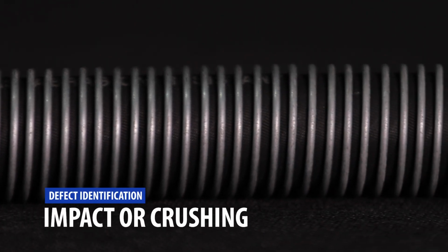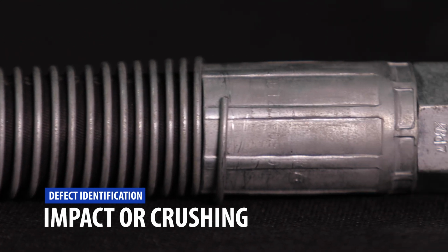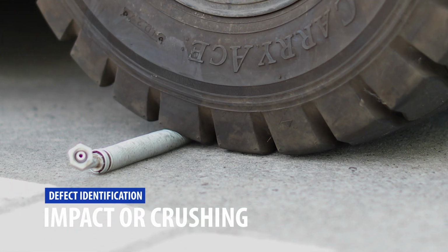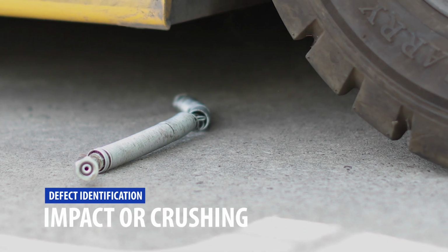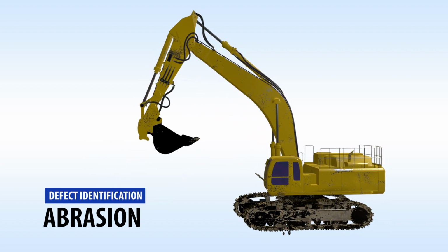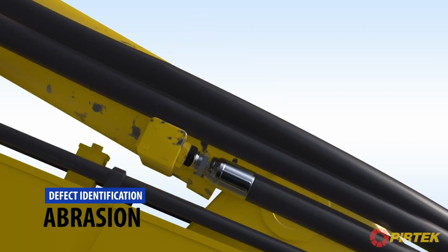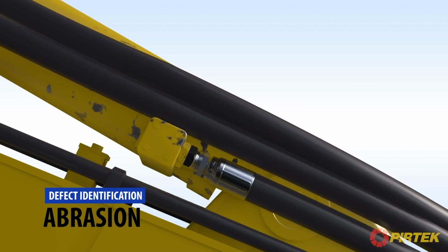Impact or crushing. Even hoses fitted with the steel spring guards are not immune from mechanical damage. The internal structure of the hose has been significantly damaged. This hose would in all probability burst if put back into service. Abrasion. Hydraulic hoses are used in tough applications and conditions every day. Abrasion is caused by rubbing of the hose against another material or even another hose.